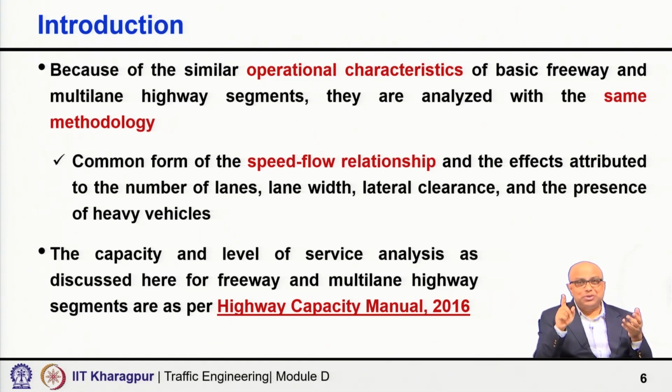Exactly the speed-flow relationship is not the same. Obviously, that will vary from one freeway to another or one multi-lane highway to another, but the form of relationship is the same, and the effects attributed to factors such as number of lanes, lane width, lateral clearance and presence of heavy vehicles are common in both types of facility.